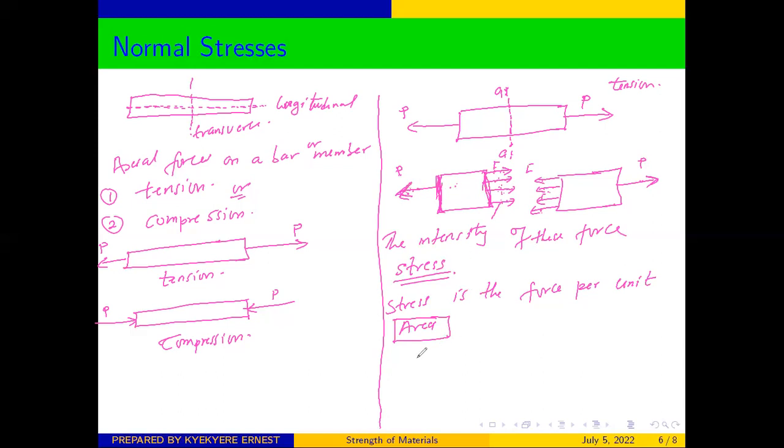It should be perpendicular. So from here, because stress is the force per unit area, we can say that the formula for stress, sigma, will be equal to the applied load P over the area perpendicular to the applied force, A. This is the formula for stress.